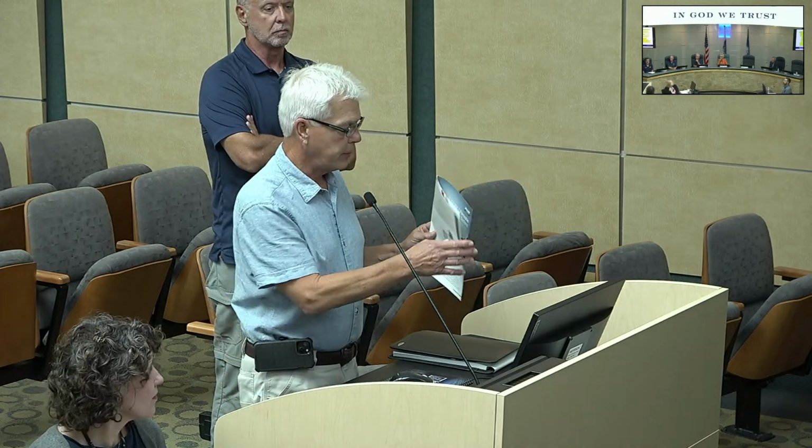I could show this, but a typical, this is a Belgard pamphlet that I pulled out of the back room, and it's basically got a 1.5 to 2 inch type 8 aggregate, and then 4 inches of 57 stone as a base, and you can get more elaborate, you can get underdrains like you saw, but for what we're looking at in the residential area, something that's going to allow some infiltration is what we're after, not just an impervious surface.